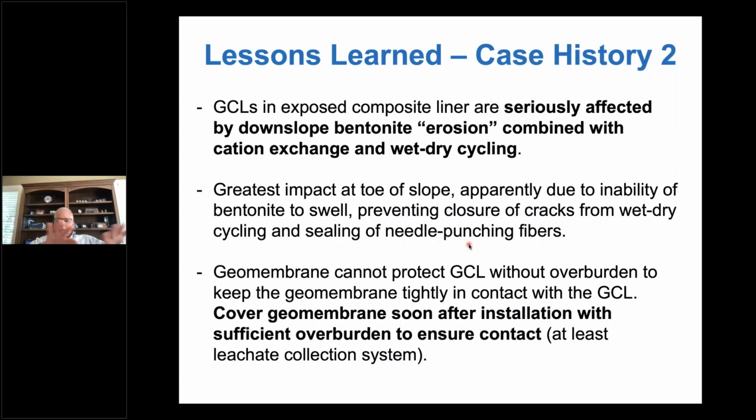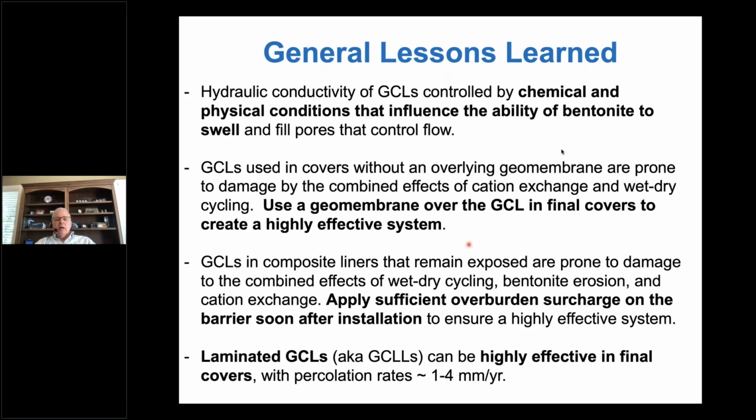So, related lessons, but for very different scenarios. Cover, liner, different physical conditions, different chemical conditions, and yet similar lessons to be learned. General lessons: one, hydraulic conductivity of GCL is controlled by chemical and physical conditions that influence the ability of bentonite to swell and fill the pores that control flow. You've seen some of these slides, the chemical conditions and the physical conditions to engineer properly with GCLs.